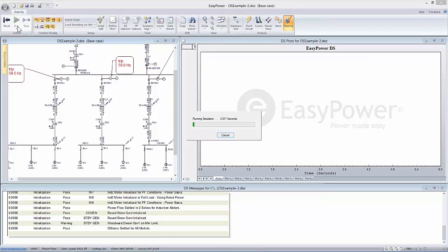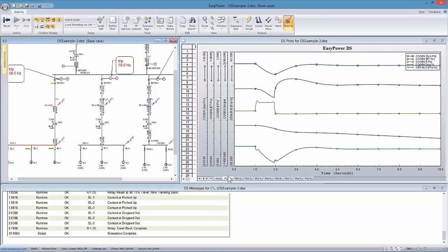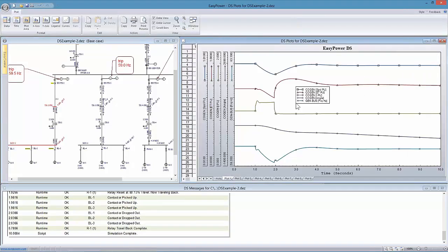So now as we run this simulation, all right, plot 1, we're looking at the cogeneration parameters itself. And we see first display is the speed, then the voltage, the current, the cogeneration angle, and then the bus frequency. This last trace down here is the bus frequency, and we can see at 1 second things were fine, and that's when the utility breaker was pulled.